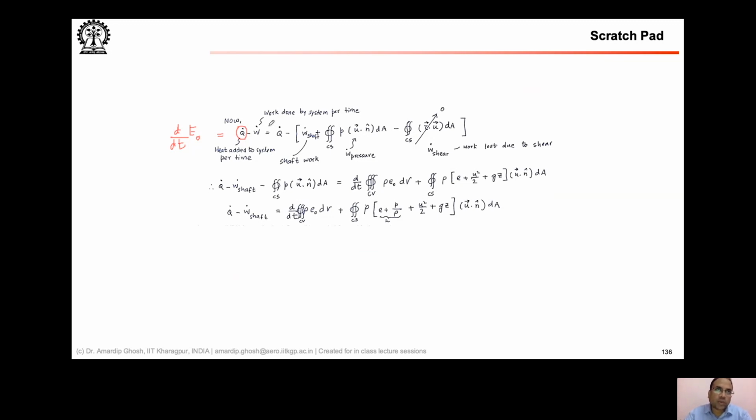In case of, say, a shock wave driven post-shock region that has become extremely hot, you will have your air going into some kind of ionization. The temperatures get very high. You might be actually radiating heat out of that system. So there your Q dot will become negative because you are giving away heat. So Q dot also has to be taken into account with the sign. W dot, by now, is the work done by the system of interest, like our fluid that is moving through the region.